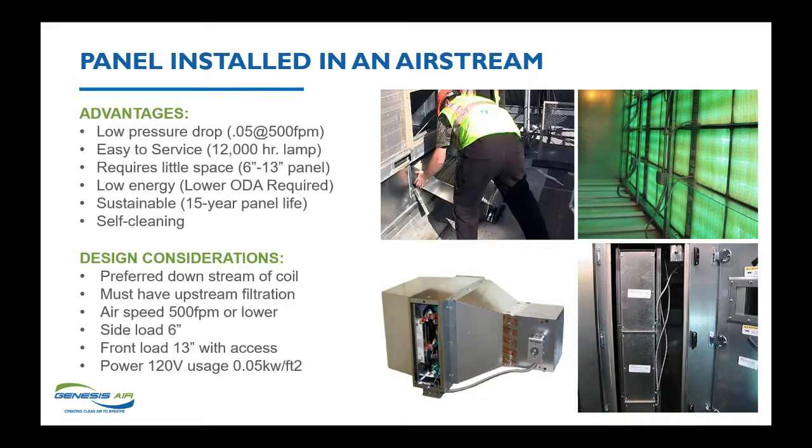Now, if the panels do get dirty, which is one of the questions that are often asked, you can use biodegradable coil cleaner on these. It will not hurt them. Also, if it's placed downstream of a coil and you have overspray from chemical cleaners, it won't hurt these panels. Low energy. You can lower your outdoor air requirements using these panels.